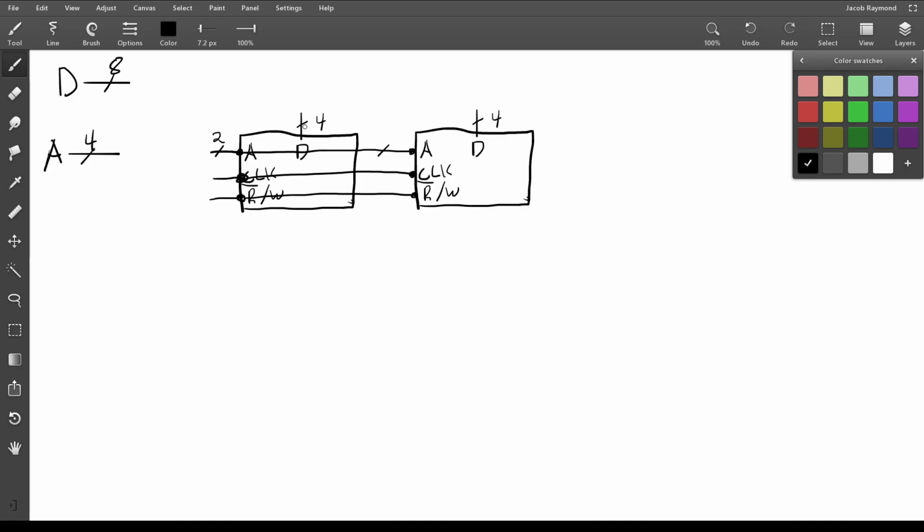So to increase the number of data bits that you have, again, just increase the width and make sure that whenever one thing happens to one, that happens to all of them. And that way, those bits will always be tied together. And really, it's almost like you have two 4-bit numbers. And in fact, that's what's going on here, because you're splitting up a large 8-bit number into two 4-bit ones and storing them individually.